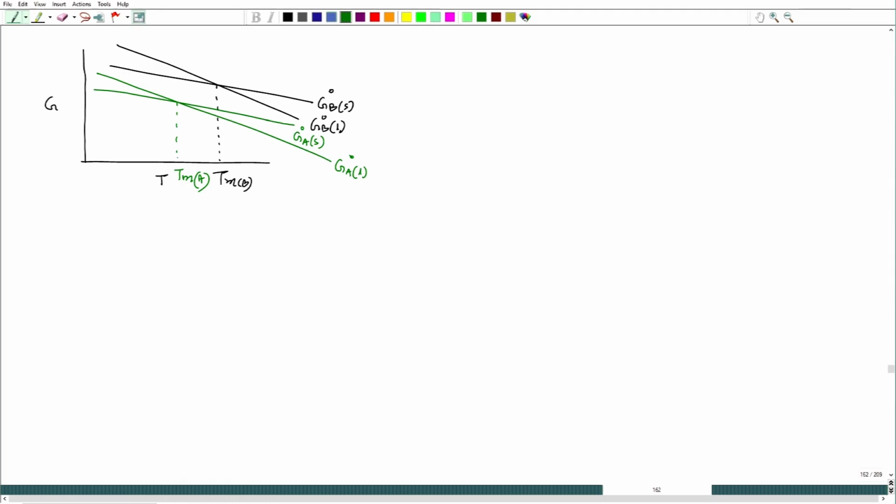But if we take this reference and a different temperature, we will plot free energy versus composition for both solid and liquid, and accordingly we will choose our stability as per the common tangent, the way we did for the isomorphous phase diagram.